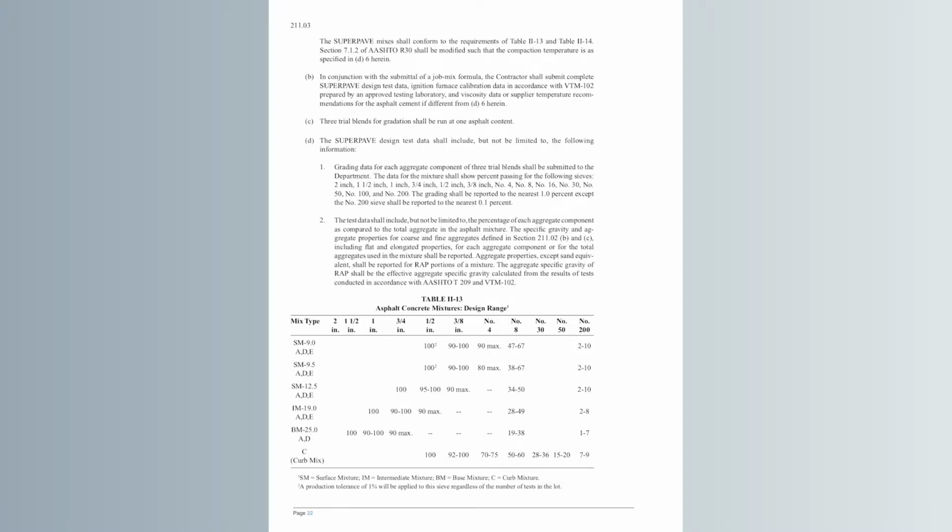Letter B talks about that you need to complete and turn in your Superpave design test data, your ignition furnace calibrations that are done in accordance with VTM 102, and your binder supplier recommendations. Letter 3 talks about 3 trial blends for gradation and how that is required.